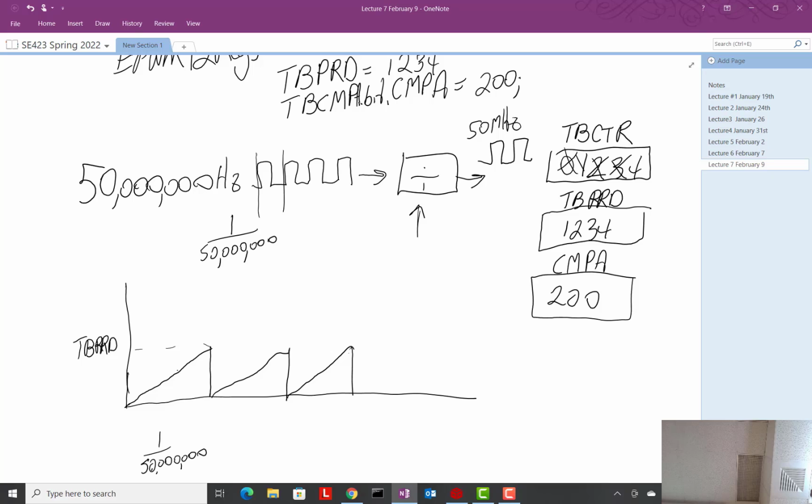Okay? So let's think about this. So what's going to happen here? This is where 200 is on this register. This is 1, 2, 3, 4, the period value. 200's right here. 1, 2, 3, 4 is right here. And it keeps on repeating, doesn't it? This is 200. That's 1, 2, 3, 4. We can, with the period, we can say whenever the counter equals compare A, I want to set the IO pin associated with PWM 12, I want to set it low.